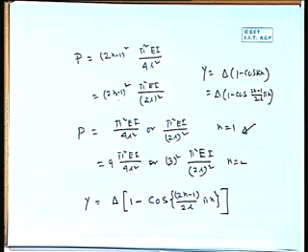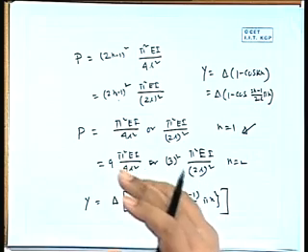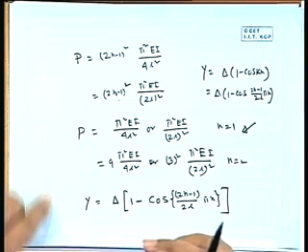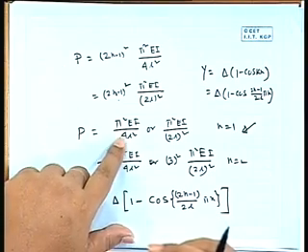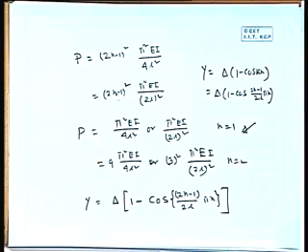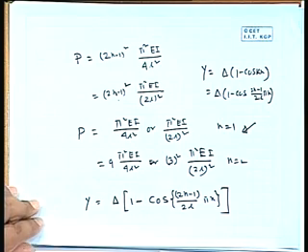That is the basic or fundamental case, because there the first mode value is pi square EI by L square. For other modes we get some factor with this, or for other boundary conditions, say cantilever, the fundamental itself is just 1/4 of that. Now we can physically correlate the two different problems, right?